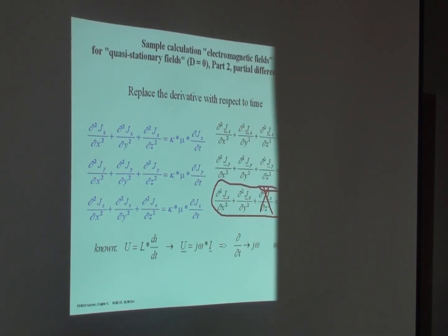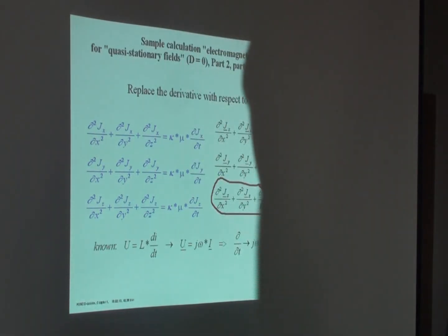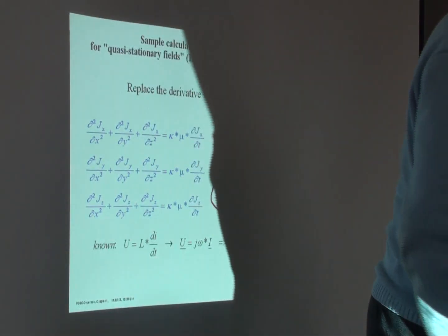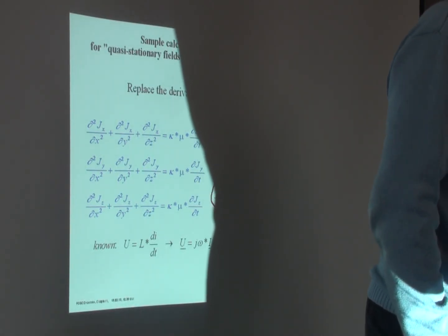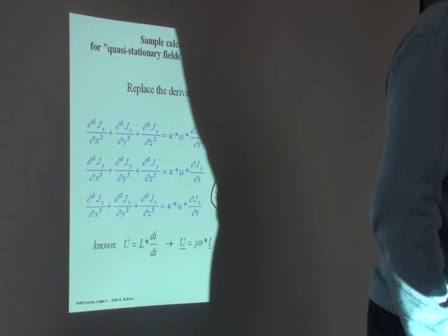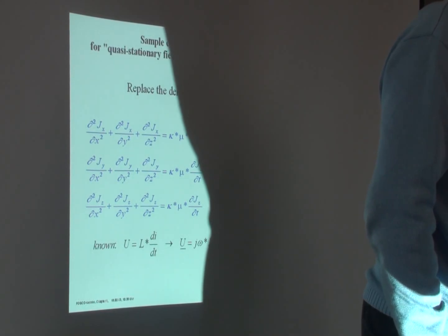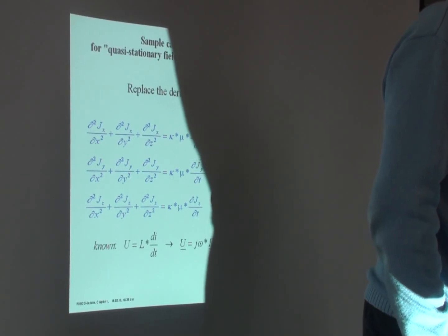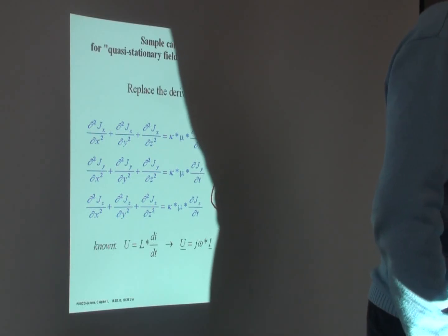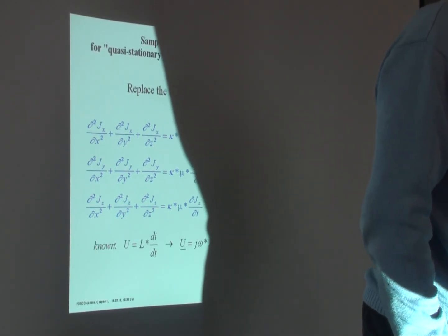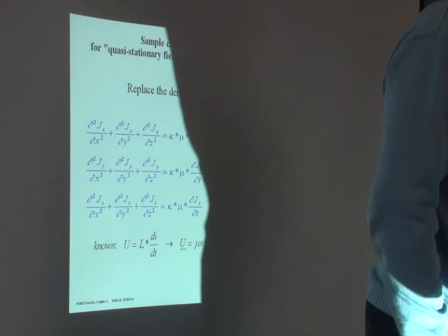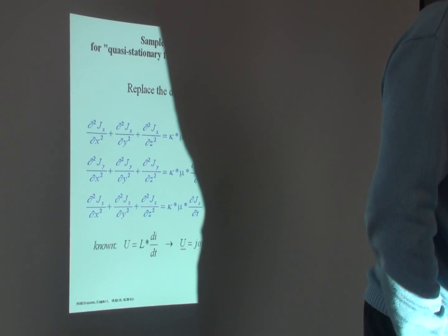I do not know how thick this was, but yes, 6 millimeters. You see that most of the current, the integral of the current density, is in this area, which is very big, and this is very small. It means almost all the current will be in the copper. It's a very important question because you have to decide, if you make copper current conducting arms, how thick the copper is. But this costs money.